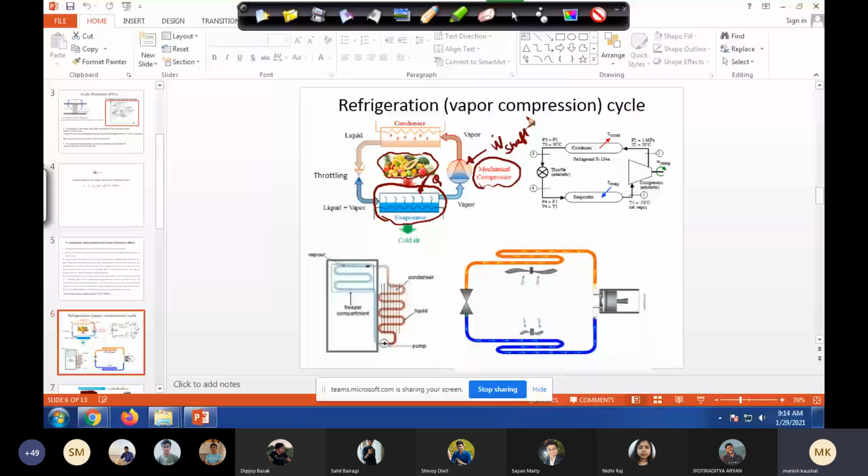So the gas is entering here, and we are compressing the gas. When we compress the gas, what will happen? If it is a mixture of saturated liquid and vapor, it will be more saturated liquid, or its quality will decrease. If this is quality X1 here, and we are maintaining quality X2 here, then X2 should be less than X1. That's what we are guessing.